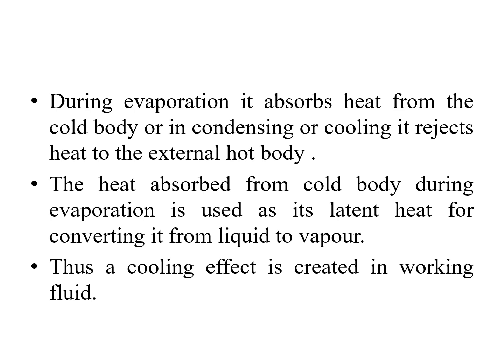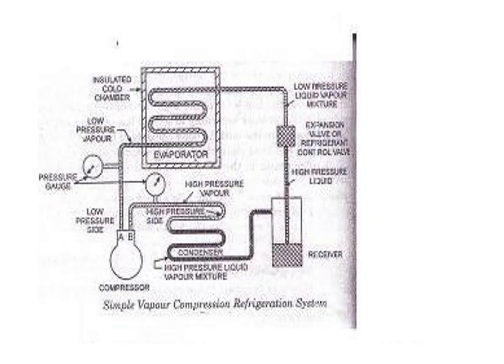During evaporation, it absorbs heat from the cold body, and in condensing or cooling, it rejects heat to the external hot body. The heat absorbed from the cold body during evaporation is used as its latent heat for converting it from liquid to vapor. Thus, the cooling effect is created in the fluid.